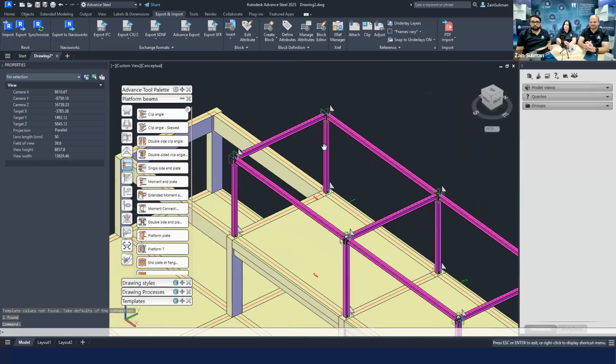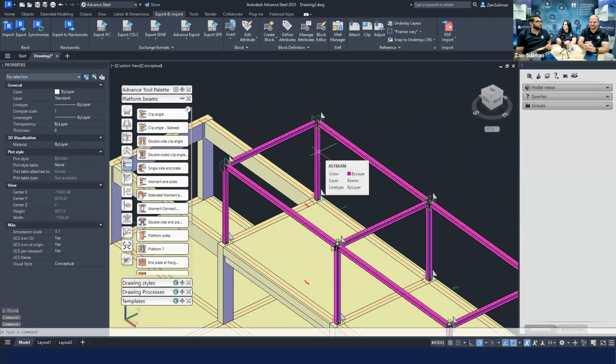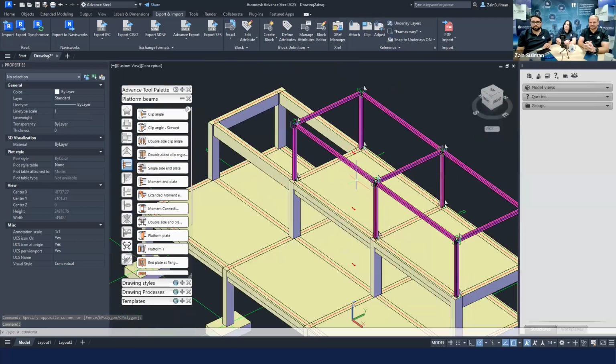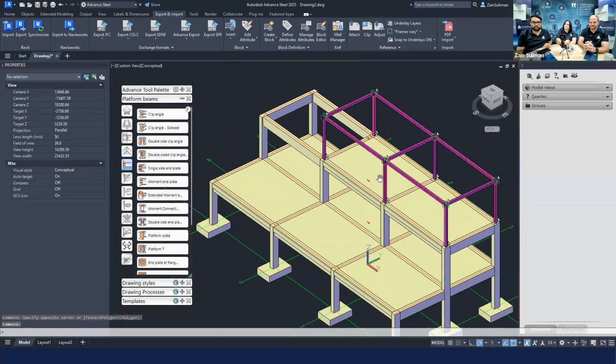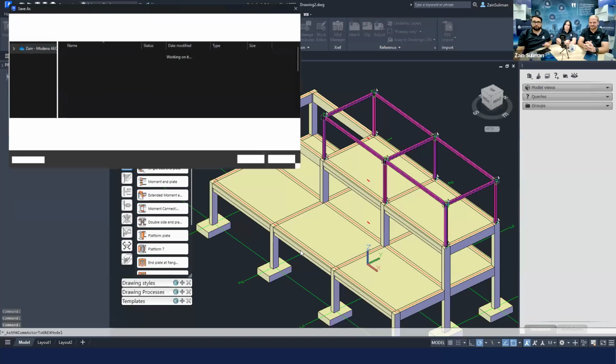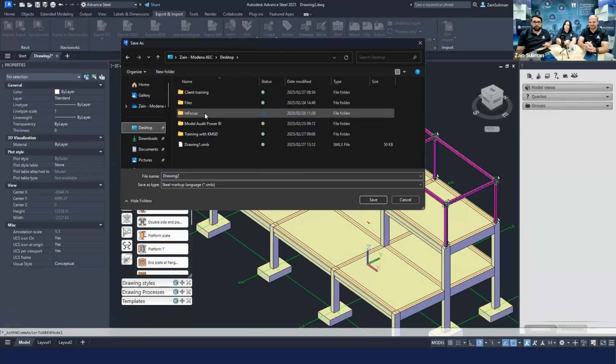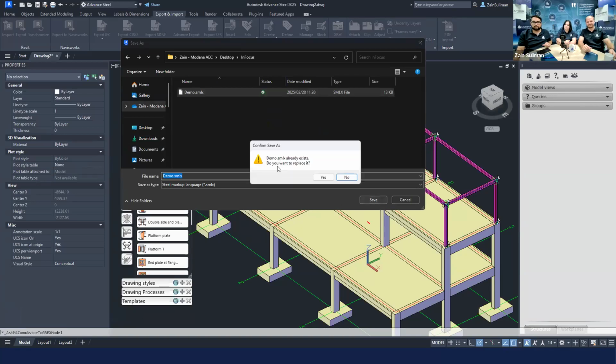Now, one thing that's important to note is not all steel members can be propagated or done for joint design. So you would want to use something like Robot Structural Analysis to analyze all your other joint types or connection types. But once I've adjusted those members, all I'll need to do to get this inside of my Revit is export this model using my Revit exporter. I can go to my file and I can overwrite this file.